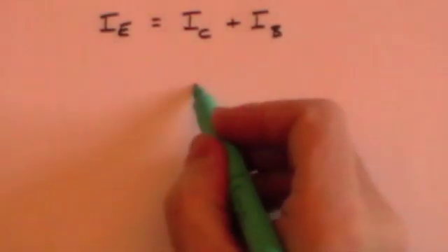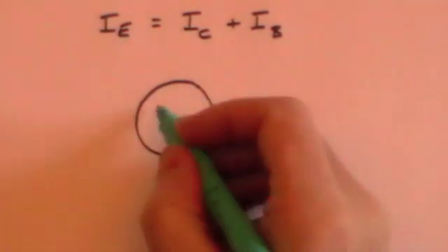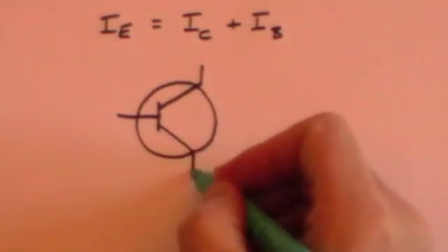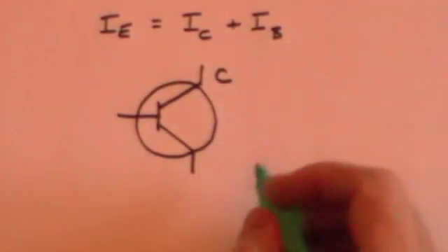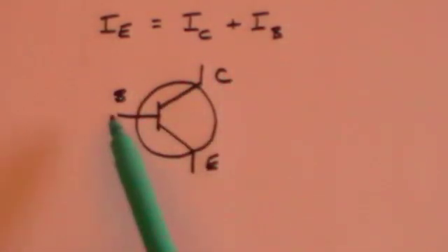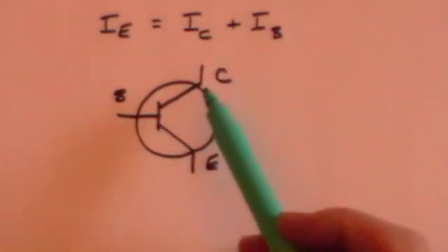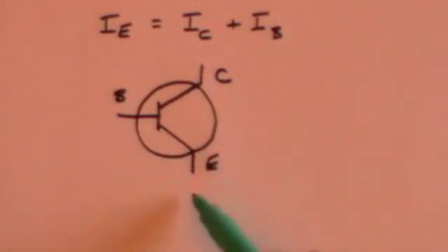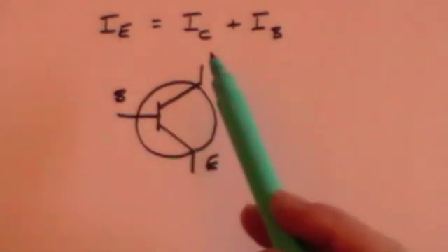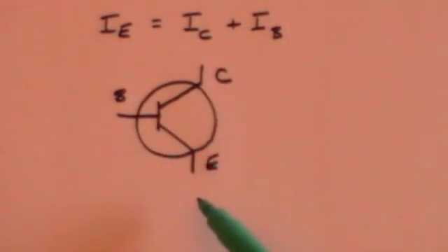And the symbol for electronic circuits for a transistor looks something like this, where this is the collector, this is the emitter, and this is the base. So essentially, provided a small current is coming into the base, it means that a conventional current will flow from the collector to the emitter and out the other side. But if no current flows into the base, then no current here will flow. Consequently, this is essentially a switch.